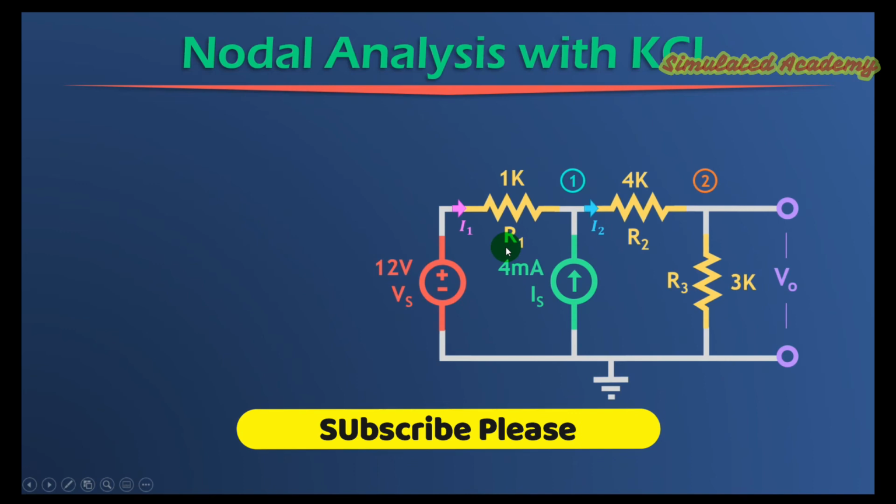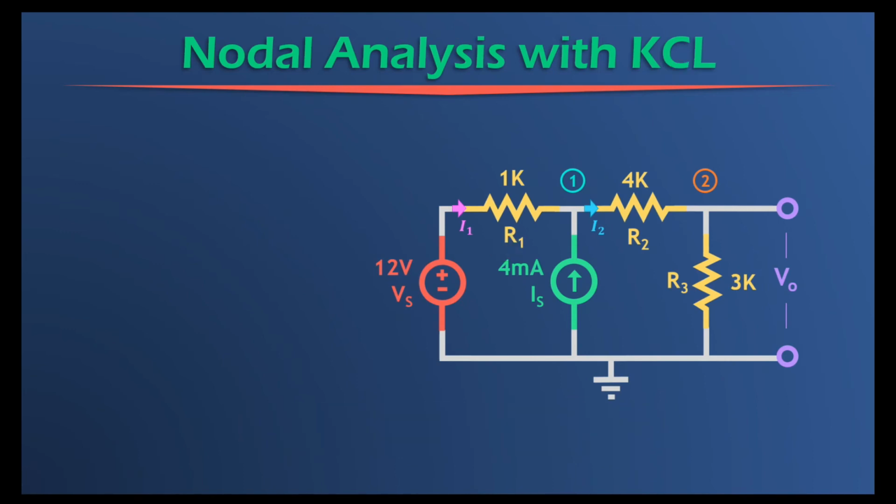The problem can also be solved using another method. In this method, we are given the same circuit and all the parameters are the same. So apply KCL at node 1. Similarly, I1 is entering, so I will take it as positive. Is is also entering node 1, so I will take it as positive, and I2 is leaving node 1, so I will take it as negative.